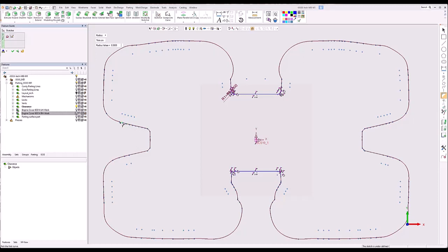All these little points here, I could get rid of all these little segments and make one curve. Sometimes I will go around and clean up this geometry. What ends up happening when I extrude it is it's going to make little slivers, and we can take a look at those in a minute.